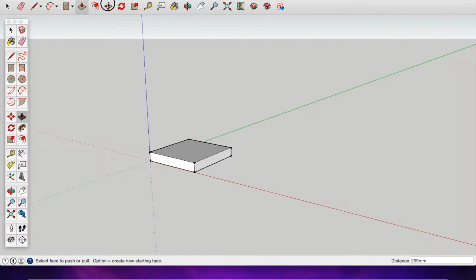Now, the tricky part about SketchUp is if you select part of this, like the top part, and I'm just showing you this, if you click and move this, it's going to distort that. You can see that it skews the seat all over the place. So I'm just going to hit escape so that I don't do that. What we need to do is tell the program that this whole chunk, this whole block, is one object altogether, and that's called making a group.